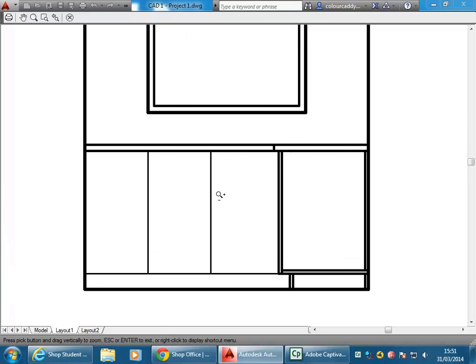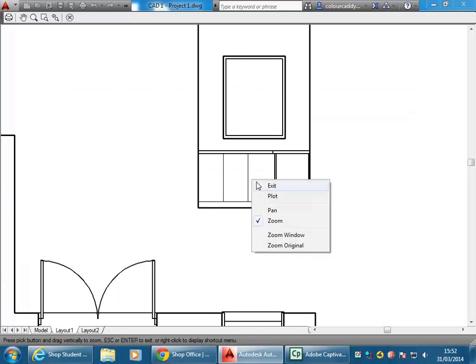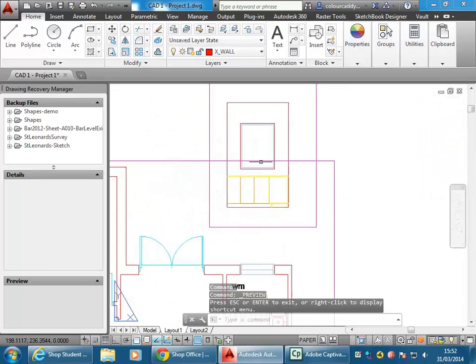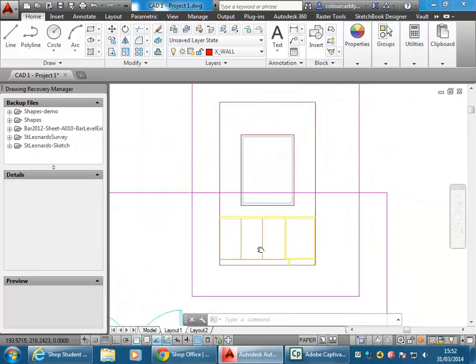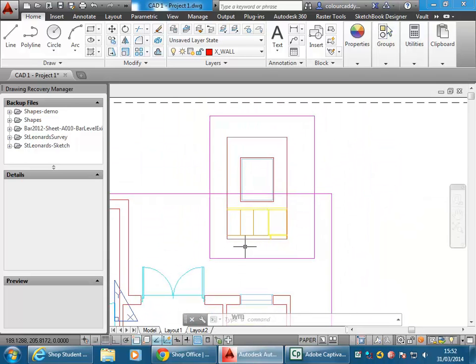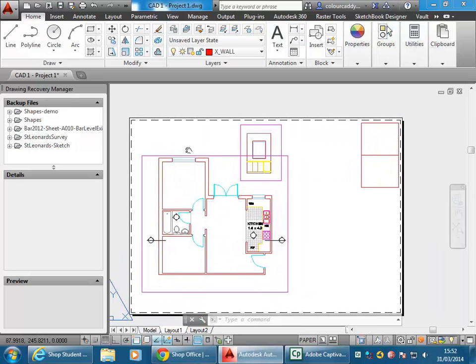And again, when you start looking at this print preview, you can get a good idea of things like the line weights, which honestly you can set up to show on the screen as you're drawing, but I haven't really shown you that because it's not worth it. When you draw in AutoCAD using the colour to set your line weight and to view your line weight, as we have been, in other words, we've got different colours here for these different lines, that is a better visual reference than trying to see it on the screen. And just when you go to do the print, you can check all of that one last time. So yeah, that's the main process.